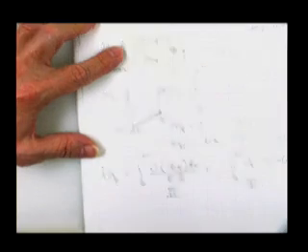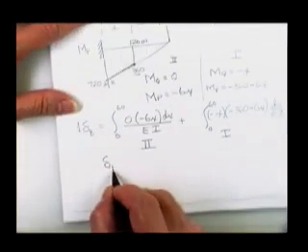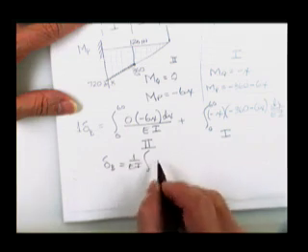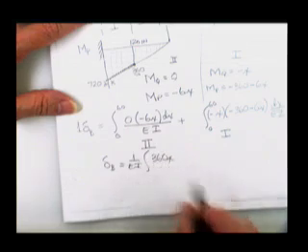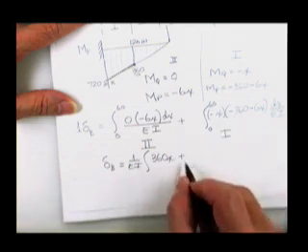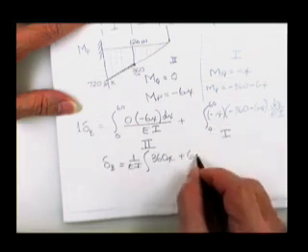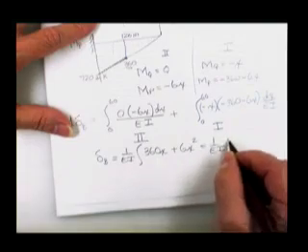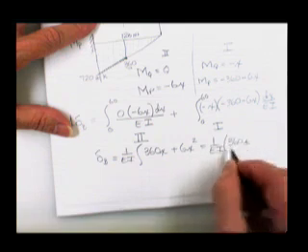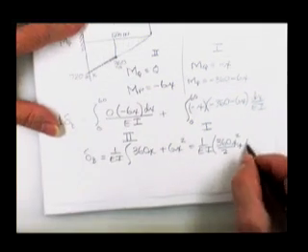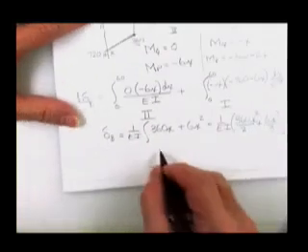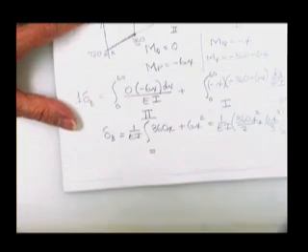In your case, it is 1 times the deflection at B. So you get that the deflection at B is equal to 1 over EI times the integral of 360x minus 6x squared, which is equal to 1 over EI times 360x squared over 2 plus 6x cubed over 3 from 0 to 60. And then you plug in 60, whatever you get.